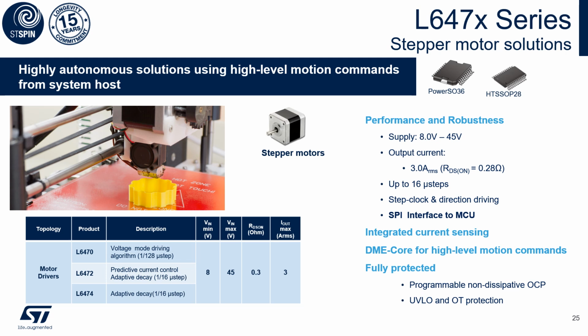They are fully protected with real-time diagnostics, overcurrent protection, undervoltage lockout, and overtemperature shutdown. They are available in PowerSO36 and SO28.